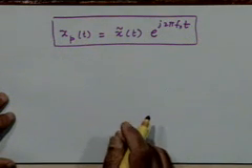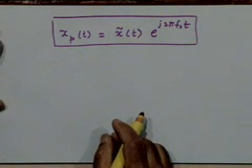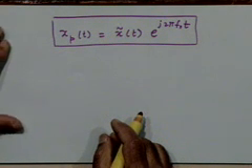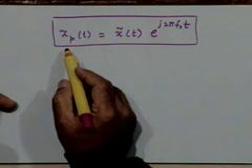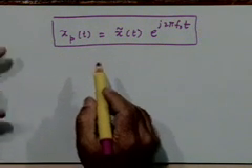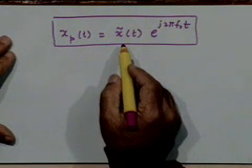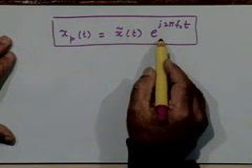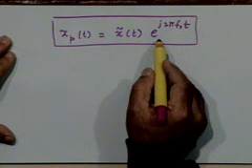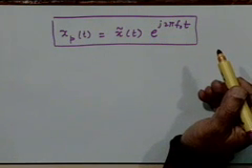Now that's a very interesting way of looking at it, right? You have already done half the job. What you have got is that the analytic version of the bandpass signal which was of interest to us can be expressed as the product of a complex valued low pass signal and e to the power j2 pi f naught t, a complex exponential, right?